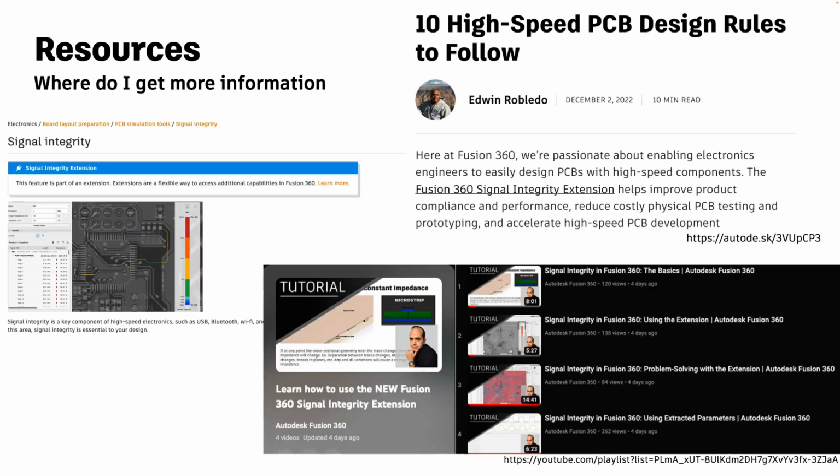Appreciate it. Jorge, was there anything else that you wanted to address from the Q&A? I saw that you wanted to answer something live. So please. You're muted, Jorge, just to let you know. That's how Zoom works. So we have a question from Jeffrey Viviani. In this case, Jeffrey, it's looking at copper. It's the fact that there's another piece of copper near the trace, or close enough that it will affect the impedance. So it really isn't concerned with the specific value of the component. It's the fact that there's a piece of geometry there that's near enough that it's going to affect the impedance of the trace. Whether it be a resistor or capacitor, for the purposes of the signal integrity simulation, the impedance of that trace, it doesn't matter. It's just the fact that there's now another element that can couple, as Matt was mentioning, either capacitively or inductively.